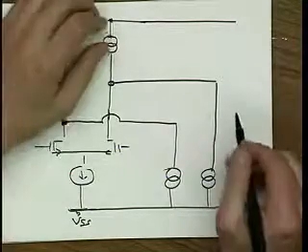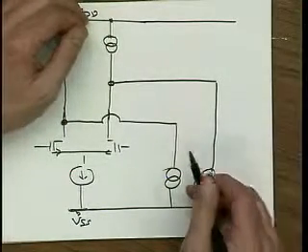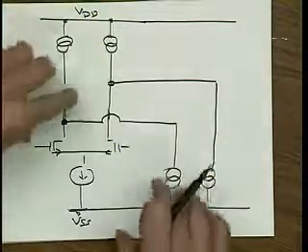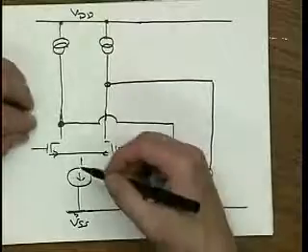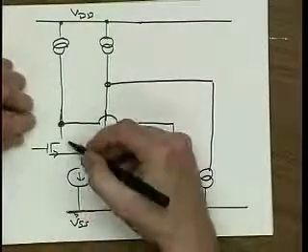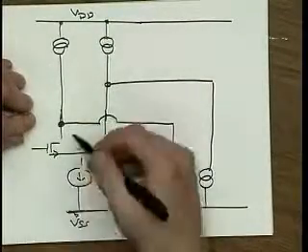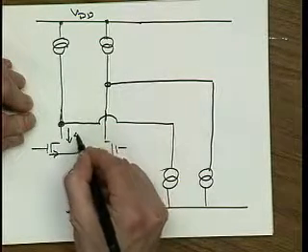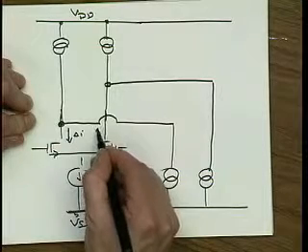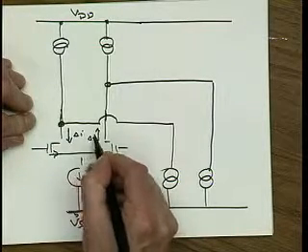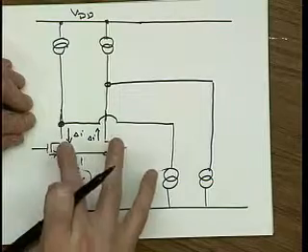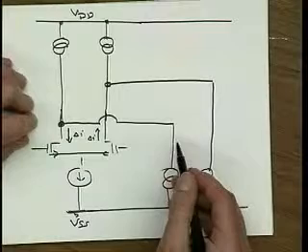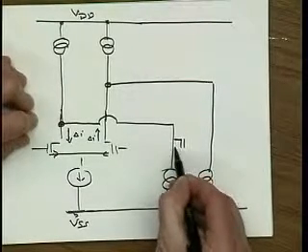And actually, what I forgot here was a cascode. So let's see what happens now. If we apply a differential voltage, then we're going to get the current delta I here, and another current minus delta I over there. Where is that current gonna go? Well, I guess I really need to introduce my cascodes here.